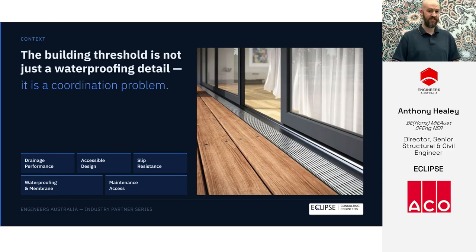If you design an accessible entry without thinking about drainage, you create a flood risk. If you design drainage without thinking about accessibility, you create a trip hazard. NCC 2025's broader Part F1 framing reflects exactly this reality. Water management now captures the full interface, not just the drain downstream.